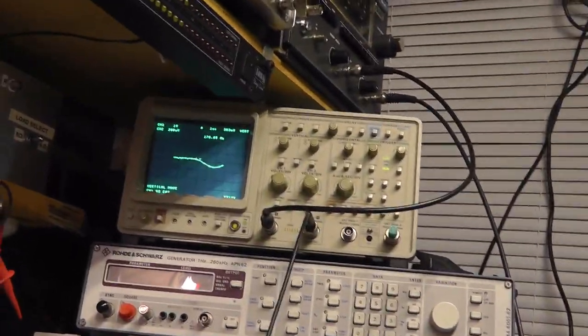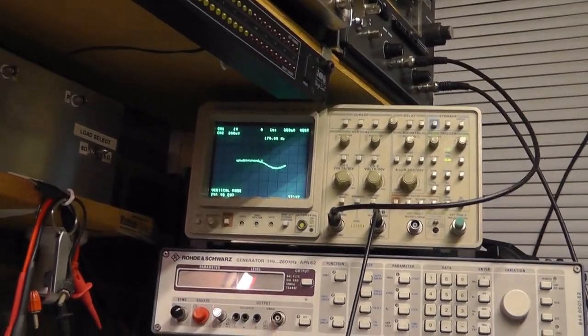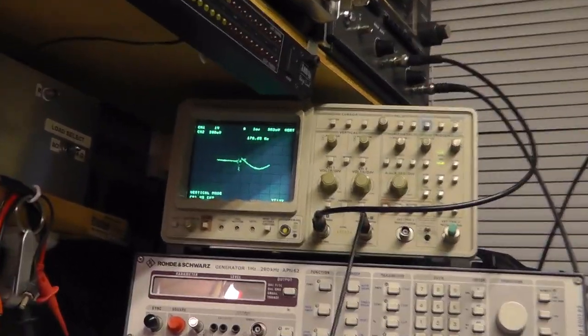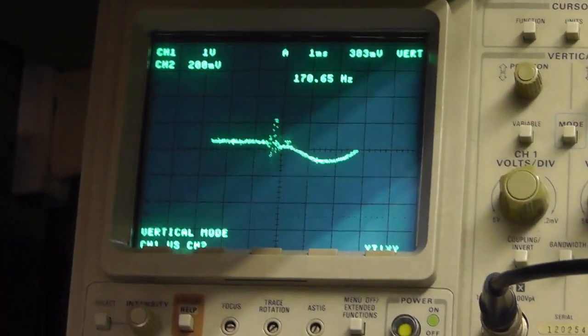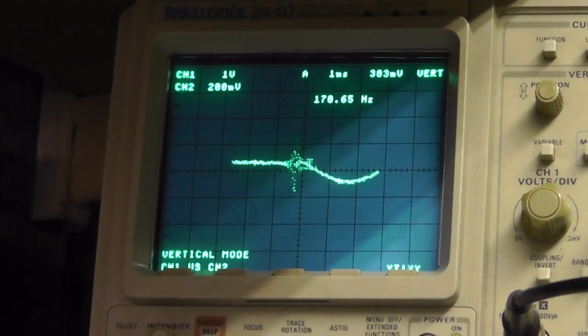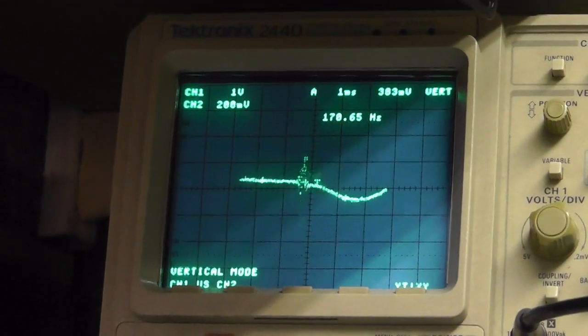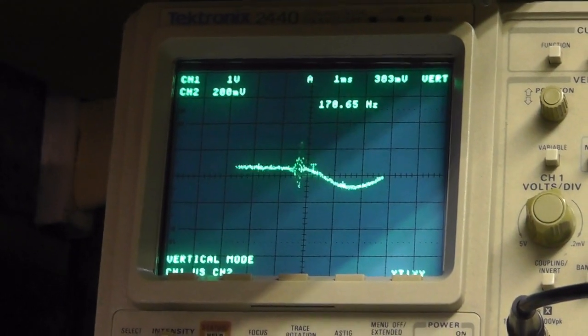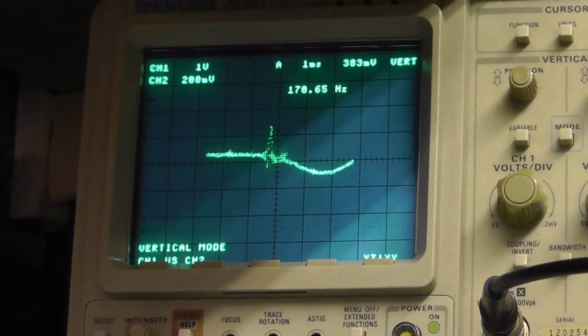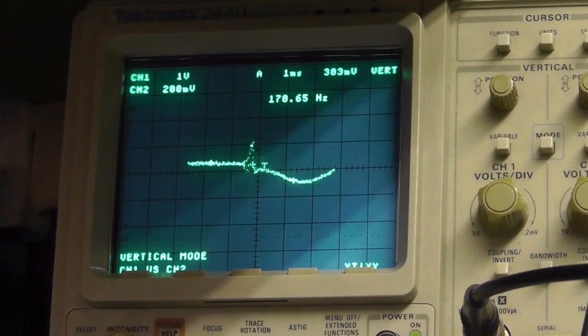Unfortunately, it's very tricky because I haven't got any tripods here. Can you see that little glitch on that marker? That's your 10.7 megahertz marker, and that's basically where the sweep's passing through, and it's beating with the 10.7 megahertz from this little marker generator. Okay, so that's what we've basically got, roughly the setup procedure, right?